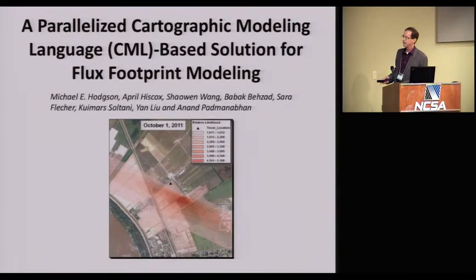This is a probability surface of the likelihood of air parcels coming during that 12-hour period from different locations on the landscape. The higher red values mean the probability is greater there. What this suggests to us is that there probably was an effluent source there, perhaps burning of sugar cane, where the ammonia would be coming to the receptor location here. But it also suggests some other things, that the 1D model we've got may have some issues involved with it.